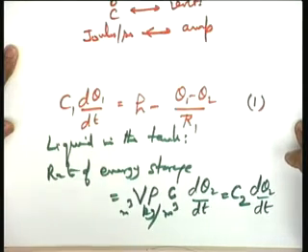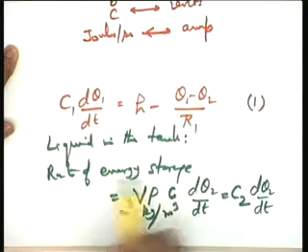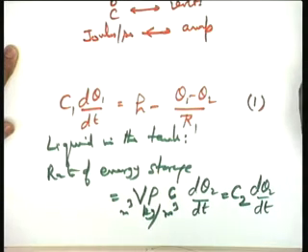Thermal capacitance of the tank liquid, the equation being I is equal to C dE by dt, E is the voltage, C is the capacitance and I is the current. You see that joules per second or the rate of heat flow has been taken as equivalent to current. Okay? I hope this C2 variable is all right for you now, and it is coming in terms of the parameters, the volume, the density and the specific heat. Okay? Now help me for the heat input and output.